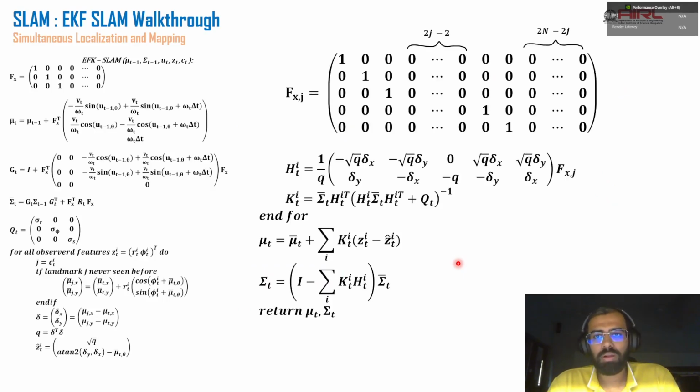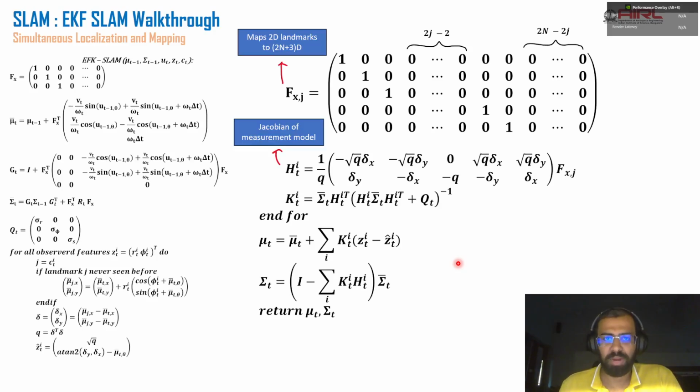Now, till now, what we had been doing was, in that fx term which we had before, we were trying to limit the state evolution due to the motion model to only my robot states, not my landmarks. Similar thing we want to try doing here, but a little differently, which is that now the observation doesn't really change my robot's position, right?